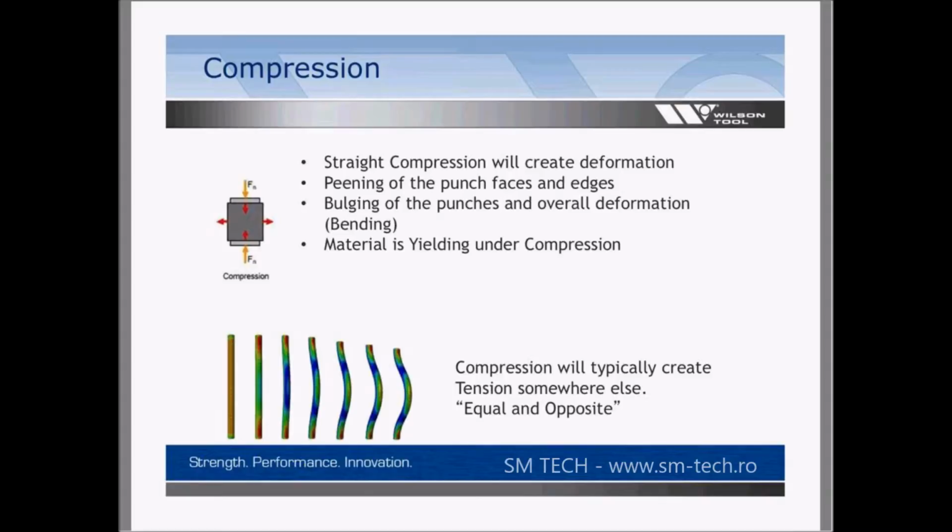So increasing it to a tool steel that has a higher compressive strength and a higher range of hardness would be recommended. If you're getting some bending in an S7 under that compressive strength, even changing that Rockwell a couple points will help. You're obviously going to lose some of that toughness, but the compression strength of S7 will be pretty good. So if you're seeing that in an M2, verify your Rockwell process, making sure your hardness is in that 60 to 63 range. If it's less than that, verify the draw temperatures and everything else, how that was taken care of.